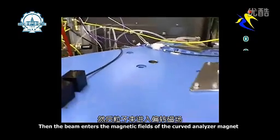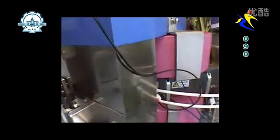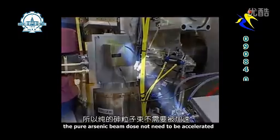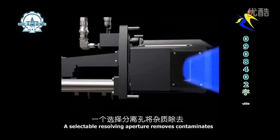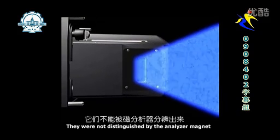Magnetic field of the curved analyzer magnet, where the arsenic ions are isolated. Because this is a shallow implant, the pure arsenic beam does not need to be accelerated. A selectable resolving aperture removes contaminants whose atomic weights are so similar they were not distinguished by the analyzer magnet.